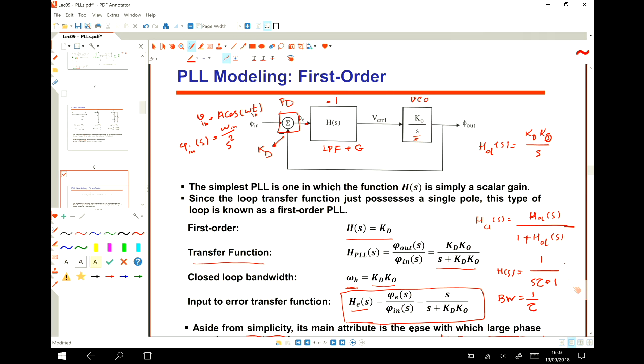It's not an integrator that gets saturated, because we are generating a phase, and as we are generating the signal, the phase increases and increases and increases. When we look at the output of a VCO as it generates a signal, the phase is always increasing. Unless we go to, for example, 360 and then get back to 0, this phase is always increasing. Okay? So this is an integrator.